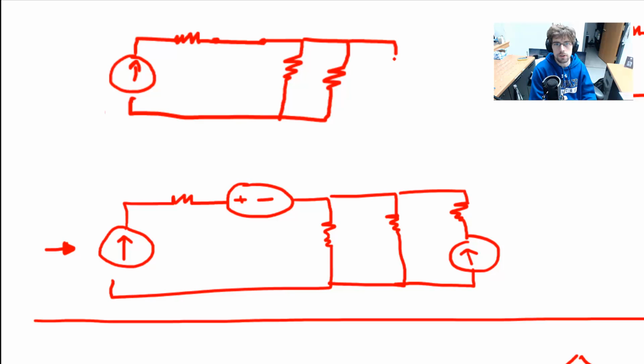And you notice that for the third resistor, I have a break, right? To remove the rightmost current supply, that's a break in the line, and so no current is going to flow in that one. So I can get rid of that piece altogether. And so there's the first circuit I have to analyze with the leftmost source active.